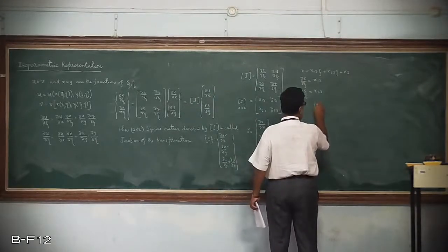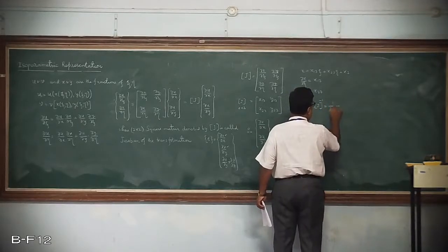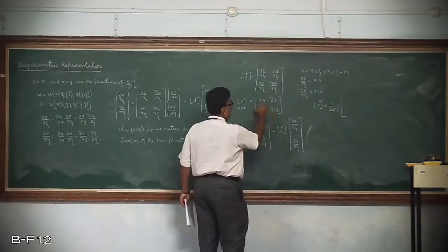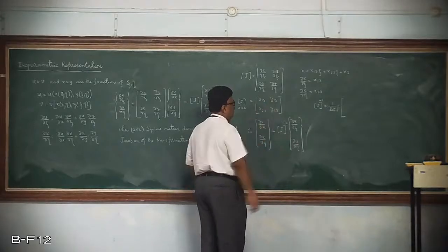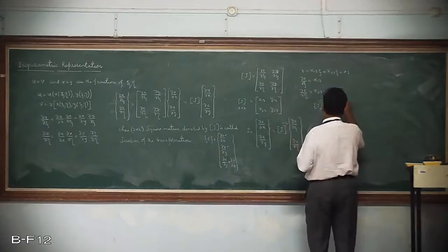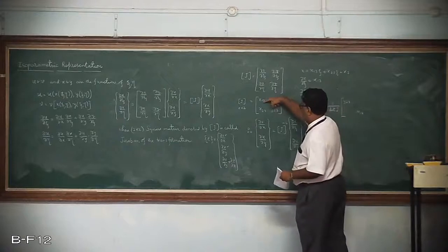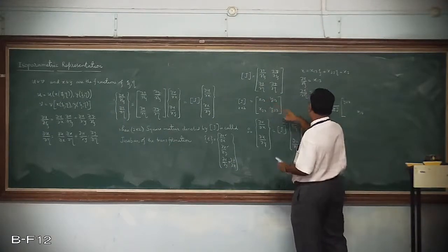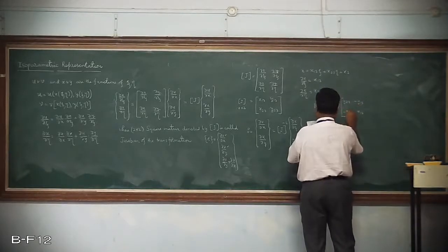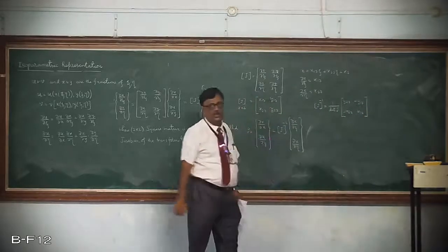Then what is the inverse of a matrix, especially for a 2 by 2 matrix? This is given by 1 upon determinant of J. Always remember these two get interchanged, and these two only change in sign. So if you write this, y23 will come here, x13 will come here, that is, they get interchanged, whereas these two will remain there with a negative sign, that is minus y13 and minus x23. This is what is called the inverse of the Jacobian matrix.